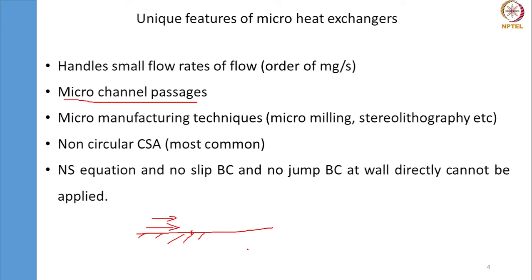However, we are not sure about no slip boundary condition in the case of micro heat exchangers. That means there is a slip condition based upon the geometry and the flow characteristics. I will show you under what conditions these are not applicable, or under what conditions we should be more aware.